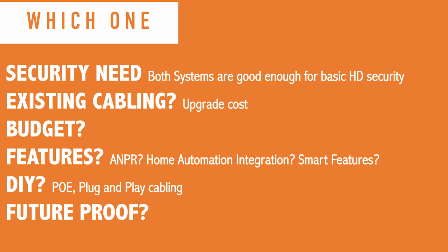Do you think your security requirements are going to exceed in about a couple of years? In which case, do you want to invest in a system that will allow that future expansion? And just on that note, if you are looking for, let's say, a 4-camera system, it's always worthwhile going for a slightly bigger recorder, let's say an 8-channel.